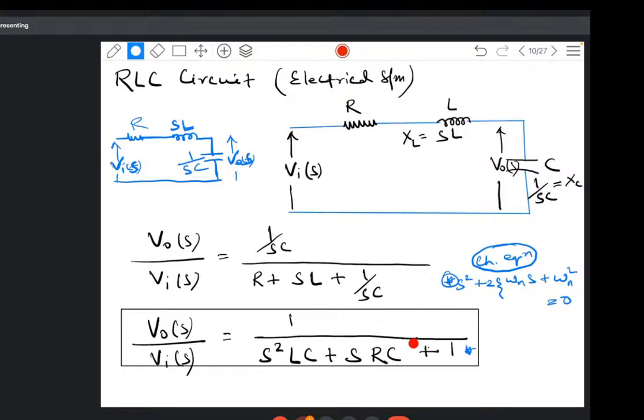So till now, what we have seen? We have seen the differential equation and the standard second order transfer function, right? Which was k omega n square divided by S square plus 2 zeta omega n s plus omega n square. Then we have seen the significance of damping. Why zeta is used? It was not used in the first order system. So why are you using it in the second order system? That theory I have given to you.